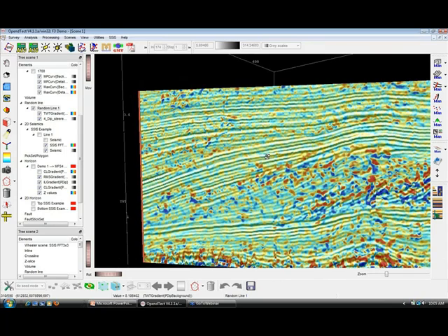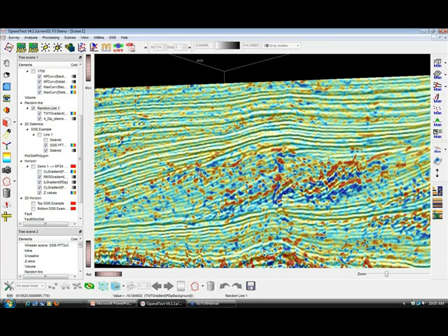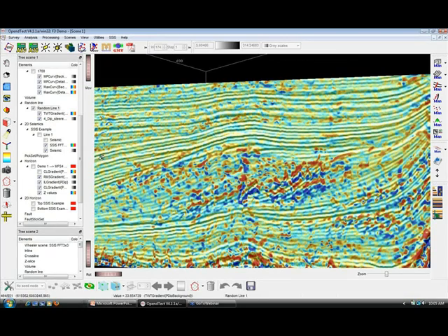I'm going to see at which locations my dip changes in the vertical direction, and those are often locations where you have angular unconformities. When you see onlap like here, when you see truncation and different offlap patterns here. Let me flip that on and off.